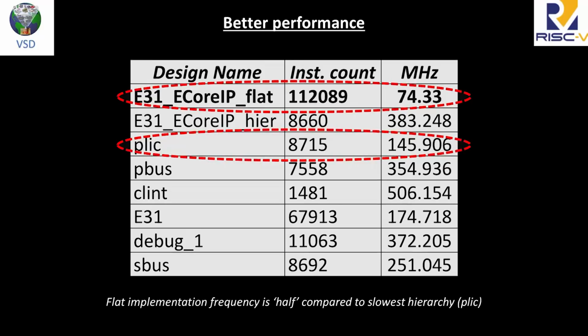We used Timberwolf for placement, QRouter for routing, and Vesta for timing analysis. And there are a few other open source tools like OpenTimer, which is an open source STA tool you can use for all the static timing analysis I have talked about. The part we want to emphasize is that all these numbers you see here are completely based on open source EDA tool analysis.